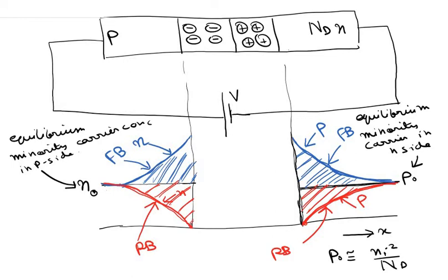So as the voltage across the diode is gradually changing, the excess charge due to the minority carriers must also change before the diode can actually accommodate the behavior of the biased situation.